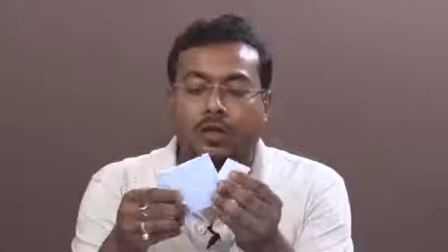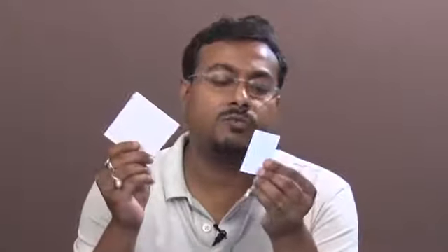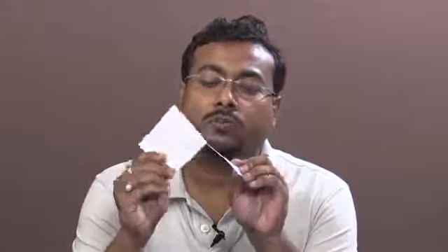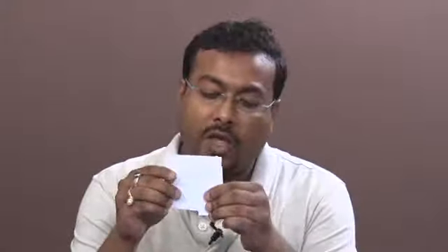Next material is foam board. Foam board is soft and you can cut with cutter, and easily you can break also. Next is high impact polystyrene. Here you can get different kind of thickness for this. It is slightly harder than foam board, and easily you cannot cut. You have to give multiple stroke on this, and then it is possible to cut. Sometimes if it is more thicker, you have to use hacksaw.